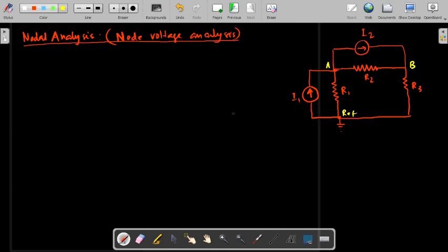Also, arbitrarily I am putting the currents of different branches where no current direction is mentioned. So I have put the current directions over here, and according to the current direction I can put the branch voltage variables with their polarity. The polarity for this resistance R2 will be plus minus VR2, and this current direction is downward, so it will be plus minus VR1, and here the voltage is downward again, so it will be plus minus VR3.